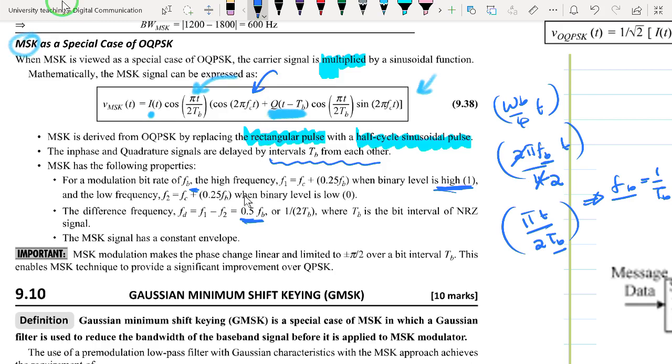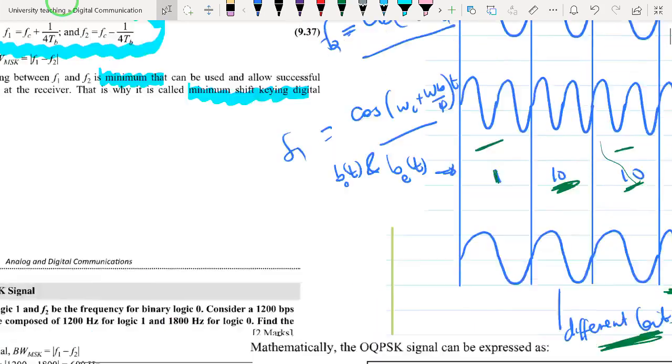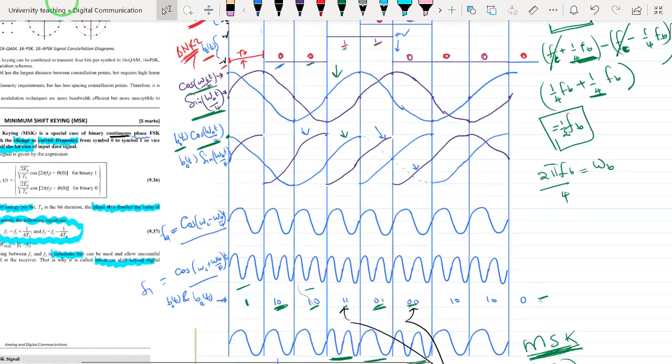that is going to be used to modulate our fast moving carrier frequency with 2πf_c, so that after we have been able to generate the in-phase component, we are then able to generate our carrier signal, combined of course with the quadrature component that is generated with the delay of T_b.